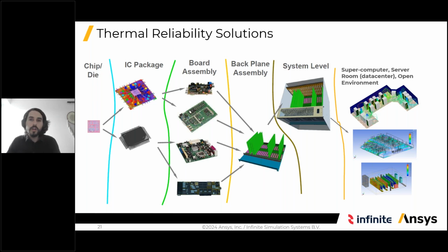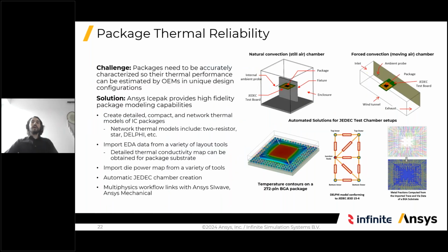Now let's take a look at how thermal simulations can help on these different scales that we talked about. So when it comes to the package, it's important to provide characterization of the thermal aspects of the package and its different components in detail, so we can have a good understanding of how the package will perform. We can efficiently extract the thermal circuit of the package as a Delphi model, so we can describe the chip performances as a single object, and then we can quickly get to know its thermal interaction with the environment.